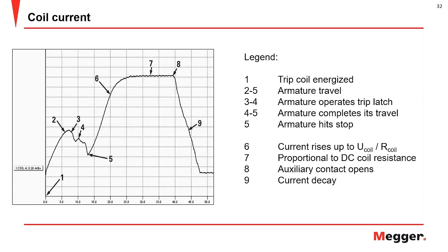So at first, the current curve shows a straight transition, whose rate of rise depends on the coil electrical characteristic and the supply voltage. And when the coil armature, which actuates the latch on the operating mechanism's energy package, starts to move, the electrical relationship changes and the coil current drops to, let's say, 0.5.